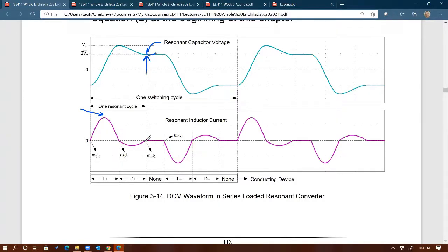The reason being, when the diode turns on, it turns on fast. It doesn't matter if it's PN or Schottky or SBR, they're going to turn on fast. The problem with the diode is turn off.